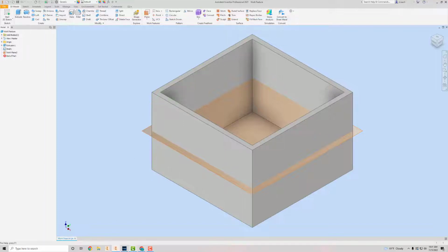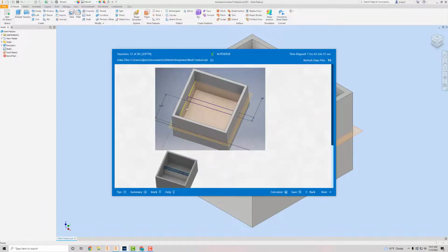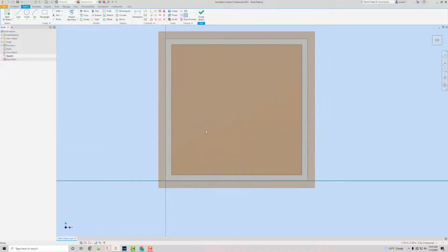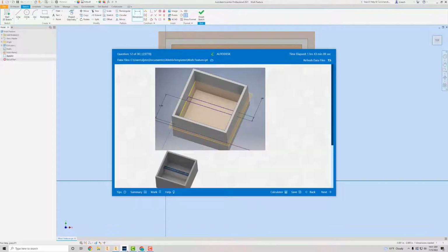I think that's what they said, -2. And then we're gonna create kind of a rectangle that's 3 inches off the bottom, and then it's 0.5. This one is a real time killer. So I'm gonna start 2D sketch on this plane that I made. I'm gonna draw a rectangle from one side here to the other. I'm going to dimension it from here to here. I think they said that was 3. That is 3.